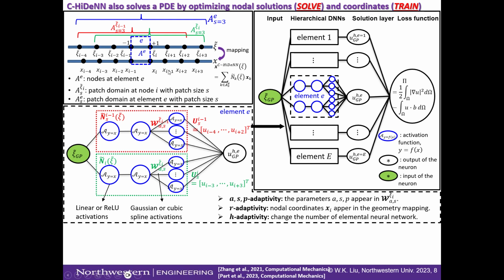But in our case, we still use the same number of degrees of freedom as linear finite element, but we leverage the nodal connectivity of the surrounding nodes to build a nonlinear interpolation. So that is a key difference, because in our case, we are not increasing the degrees of freedom, so we are still having the same, I would say, level of difficulty in solving a problem, solving an equation, but still can do the higher order interpolation or approximation.